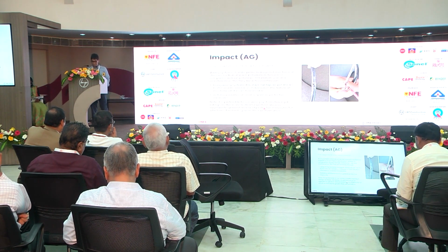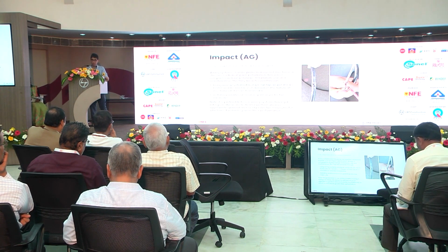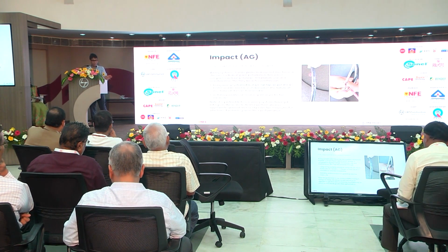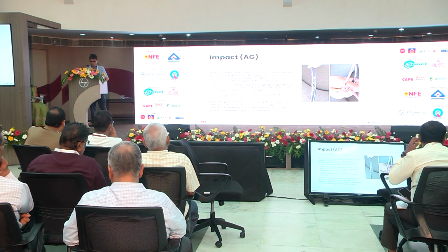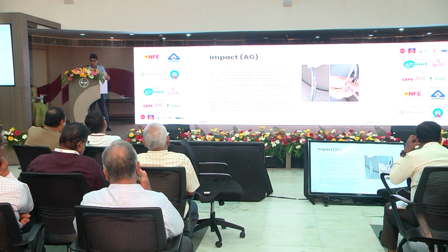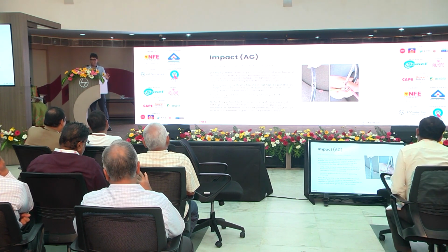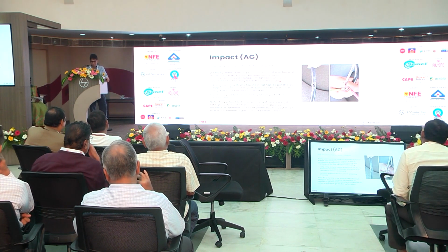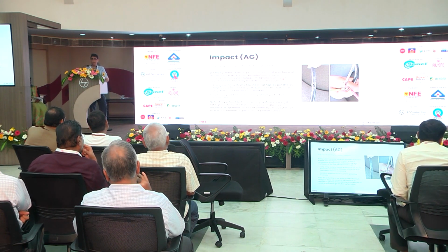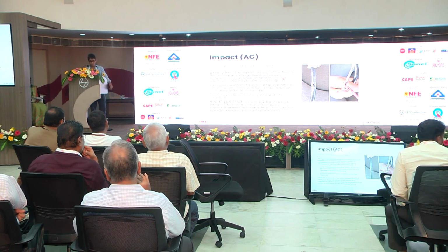Impact. So this is actually an unfortunate incident where I was there. An electrician drilled through a cable, and fortunately there was a circuit breaker that was tested and everything was fine, so no actual hazard occurred because of it. But you can see what drilling through a cable does. It completely destroys the cable. It was also fortunately an accessible cable, so you could pull it out without any problem. So impact, penetration, or even tension, and especially during storage as well, is an important consideration.